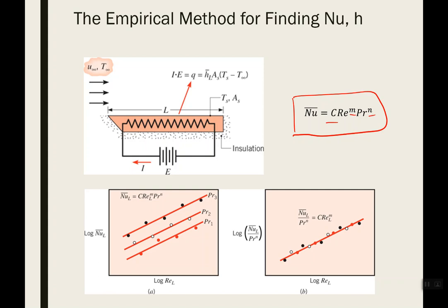So you'd collect a bunch of data, and when you're dealing with different fluids, you're going to get distinct differences in the data. But when you lump the parameters together, then you can see that they all line up. So that's why things are generally expressed in terms of Reynolds number, Prandtl number, Nusselt number, because those tend to sort of unify some of the effects. So if you did a bunch of experiments with air and did a correlation, well, your results would probably just apply to air.